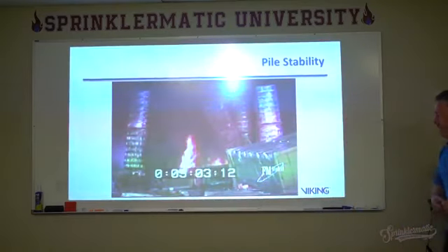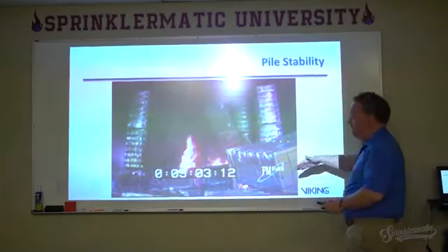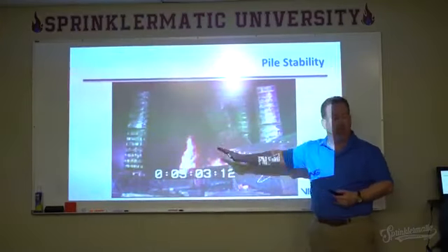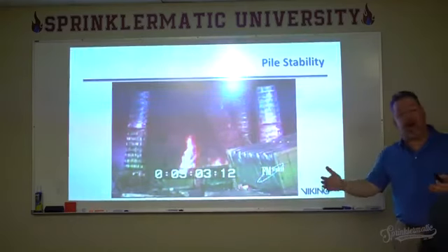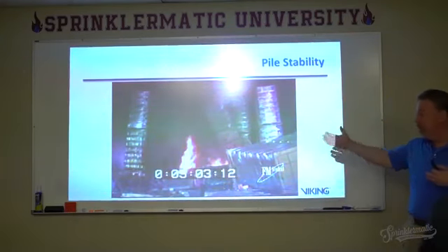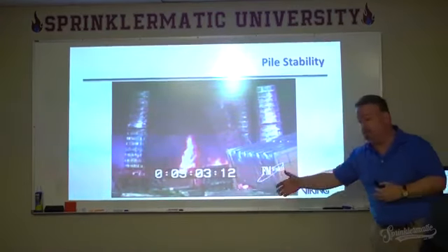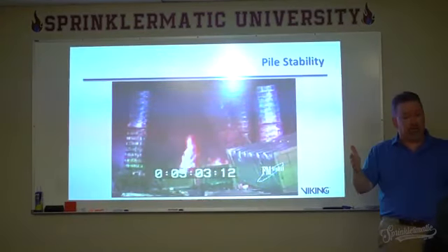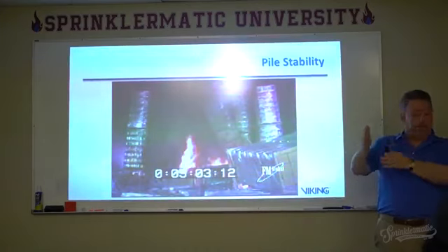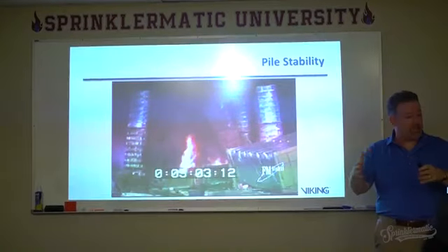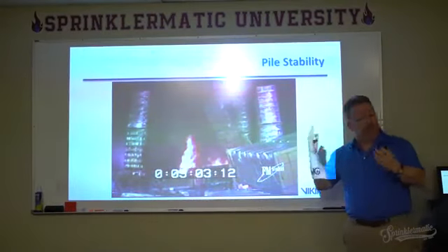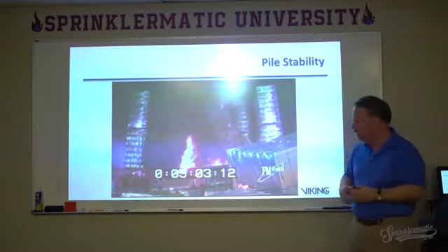All right, pile stability. Here's an example of a fire test that was done, and the piles began to fall over on themselves. If we've got stable piles, those are a higher challenge, because they stay up. Whether they're using wood pallets or reinforced plastic pallets, they stay vertical, which means that the air stays around all of the pallets and the stored commodity, and the fire will grow.